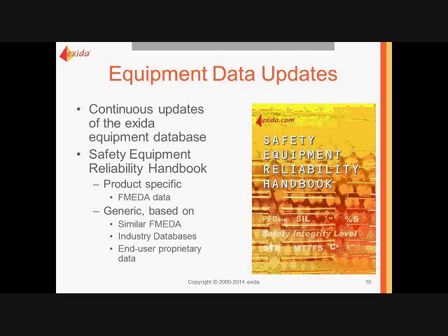It's certainly not based on cycle test. Cycle test data is not used at all. We believe that cycle test data can be very misleading, especially for low demand and especially for final elements, because if you have a valve in a low demand mode, it's going to be static most of the time.